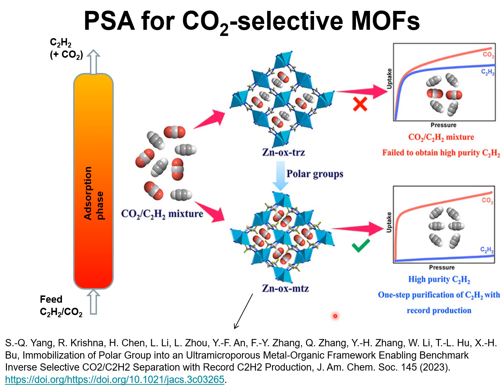the pores are such as to allow for a significantly higher uptake of CO2 in comparison to C2H2, with the result that purified C2H2 can be recovered in the adsorption cycle of a PSA scheme. This allows for higher product purities to be achieved at high C2H2 productivities.